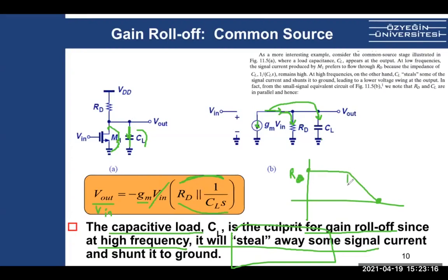So this cutoff or roll-off is basically a frequency called 1 over RC, angular frequency, so omega. Okay? So at the specific frequency where omega is 1 over RC, I start to see 3 dB, which means the gain drops by square root 2. Okay, so why is it 3 dB?